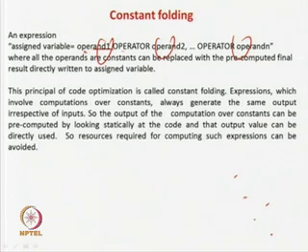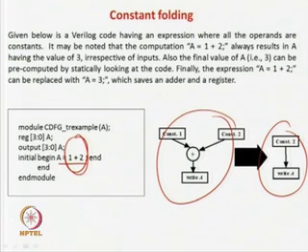So, the expressions which are computations over constants always generate the same output irrespective of inputs. In this case, you can fold your constants and make it one value. You save an adder, and sometimes you can save a multiplier and so forth.